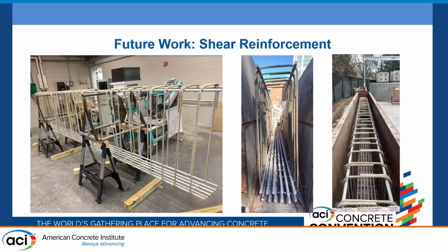The other thing, again related to the cracking rebar: I saw that in some research you mentioned that they didn't have stirrups. Right, it was just the longitudinal reinforcement at the base. Based on CSA for FRP, CSA for steel, or ACI for steel, we need to have some vertical rebar to avoid cracking. So I don't know why they didn't put any vertical rebar or stirrups in their research.